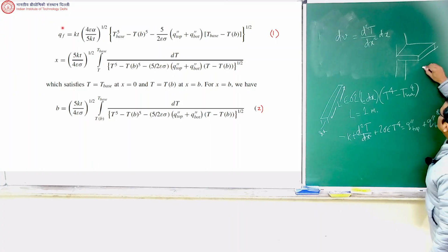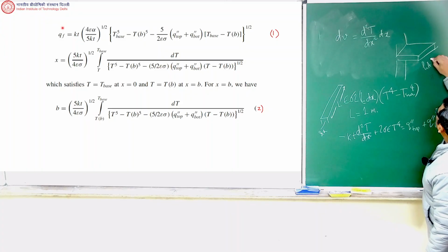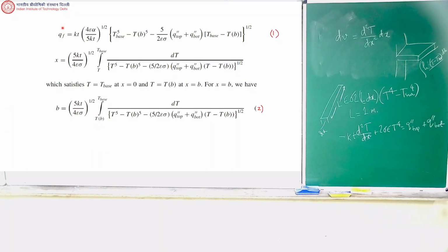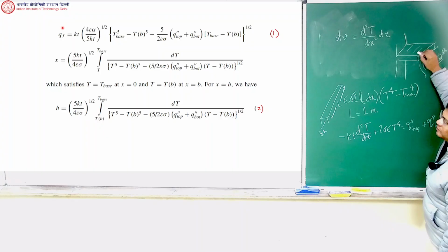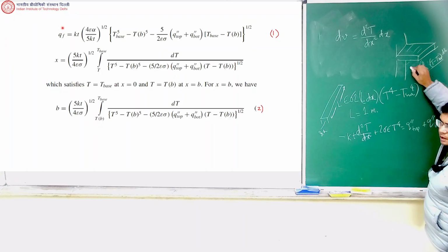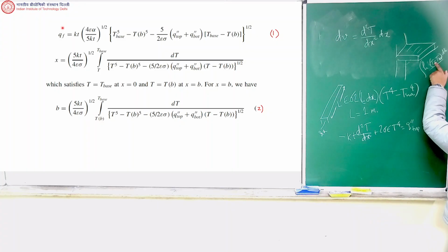One is that you say h(T minus T infinity) dA, and you can integrate this, right? Because the heat transfer takes place by convection from the top and from the bottom. So if you do h delta T dA and then integrate over the entire exposed surface area, then you will get heat transfer. That is one way of getting it.